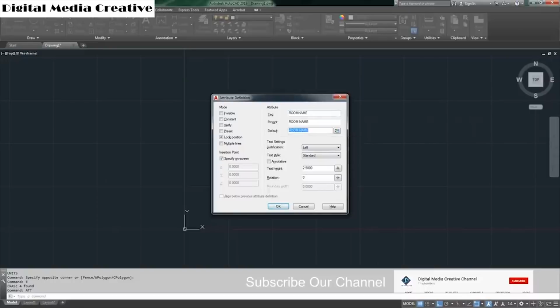Okay, so the next one, you can go to the text setting. Then I always prefer middle center, so whenever it's bigger or smaller, it stays in position. And you can also choose the text style, if you have a special text style. And for ISO standard, I always choose the text height as 2.5 for 1:1 scale. Okay, so this is a common setting. Then you can press OK.